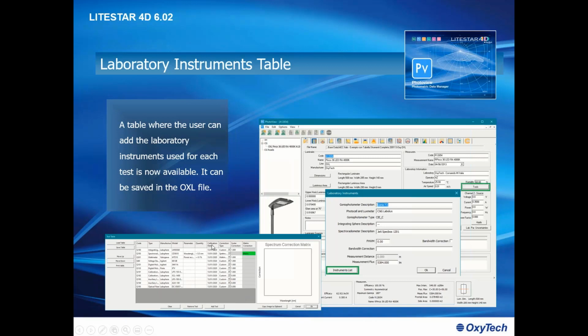And first of all, you can also define the calibration expiration date, so a full set of information. You can also input the correction factor if you send your instrument to a laboratory and it comes back only giving you a value which you have to apply. The program will automatically apply the correction factors to any of the available parameters.